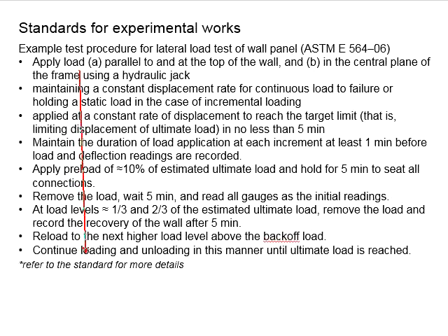These are the list of the procedures as outlined by the standards. Apply load parallel to and at the top of the wall and in the center plane of the frame using a hydraulic jack. That means this gives you an idea where you should apply the load, and then maintain a constant displacement rate for continuous load to failure, or holding a static load in the case of incremental loading. This gives you two options of increasing the load.